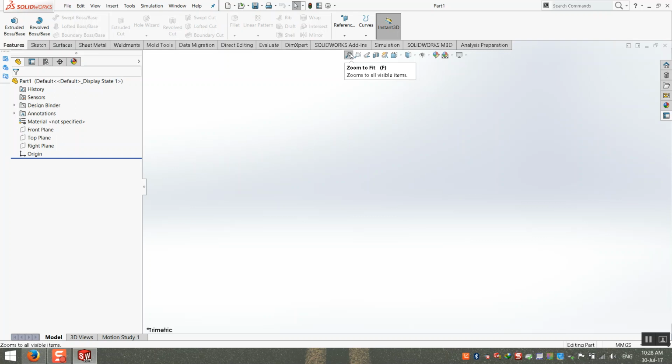Now, this is a door and this field. The application is only opening and closing. It doesn't have any extra loads. This part doesn't carry something with 1 ton, 2 ton, 3 ton. This means that this application is only for opening and closing. You may not need to make this 2 millimeters sheet metal. You can save material with 1.5, for example, 1.2.